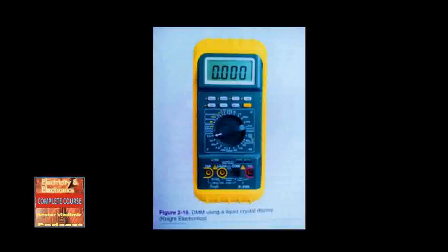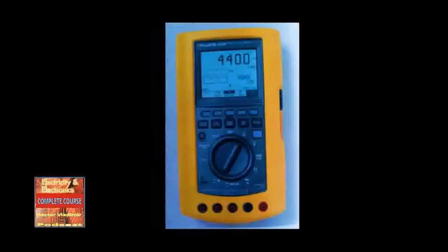However, some technicians still prefer the analog meters for taking certain types of readings involving solid-state circuits. This will be explained in more depth when solid-state electronic devices are explored. The liquid crystal display shows the meter reading in digits rather than on a scale. Some DMMs simultaneously display digits as well as a bar graph that simulates a linear scale reading. Figure 2-17. Digital meters not only measure volts, ohms, and current, but also can test electronic components such as transistors and diodes. Figure 2-18. The digital multimeter can come with a rotary dial, like the analog meter, to select functions, or a keypad that is pressed with the fingertips.